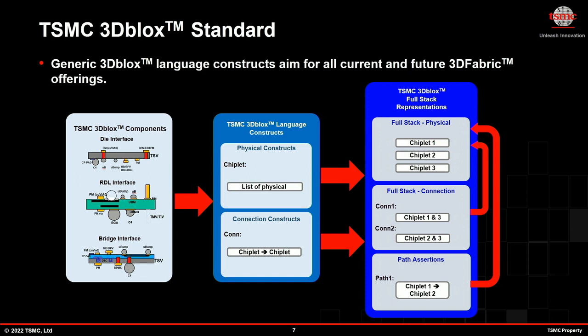Then, since it's all about interfaces, we explicitly designed the connection construct that captures where these chiplets are exactly connected. So with this set of generic representations, we can build a full 3D IC stacking representation with this kind of language syntax and semantics. And we also add the assertions that can continuously check your implementations to make sure certain properties do exist.